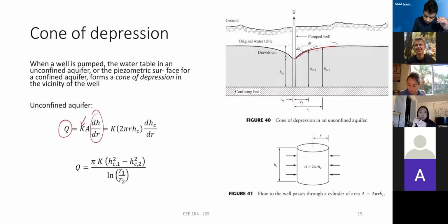So this is called the zone of influence. That means if you pump at a certain rate, within this area all the water will be experiencing that drag. Beyond that zone, you will not experience any head differences. So this is the zone of influence or the cone of depression. Beyond this, your dH equals 0.